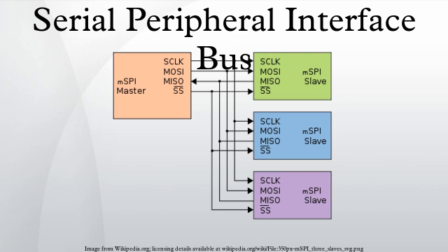For high-performance systems, FPGAs sometimes use SPI to interface as a slave to a host, as a master to sensors, or for flash memory. Used to bootstrap if they are SRAM based.